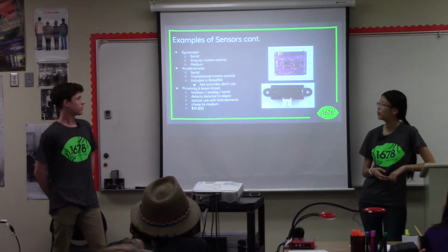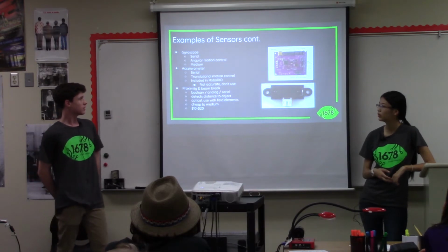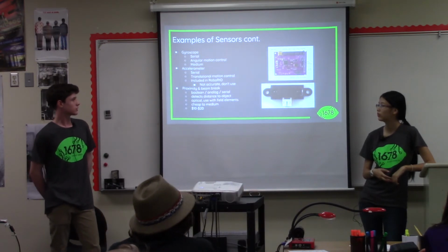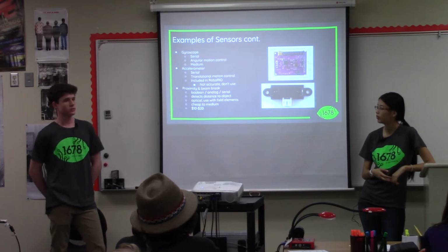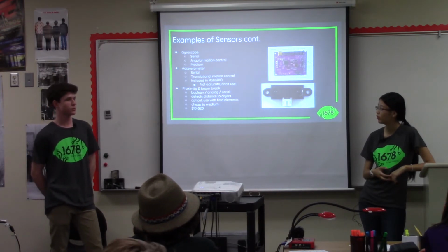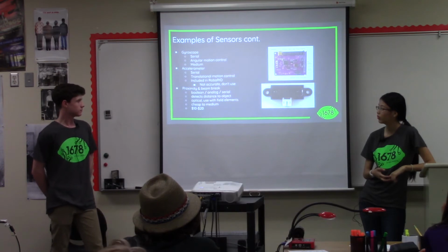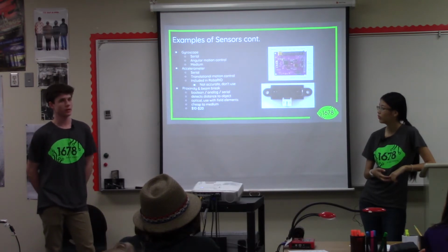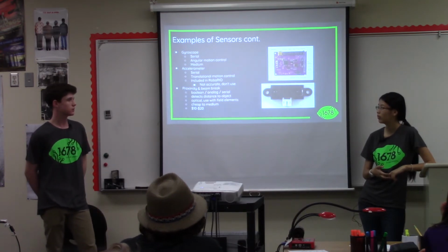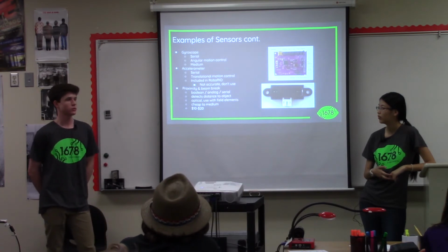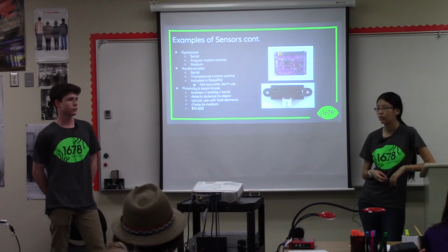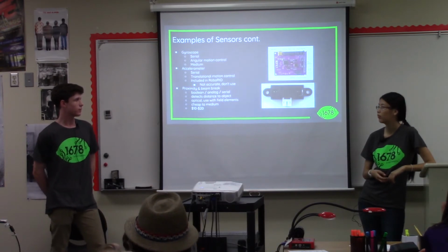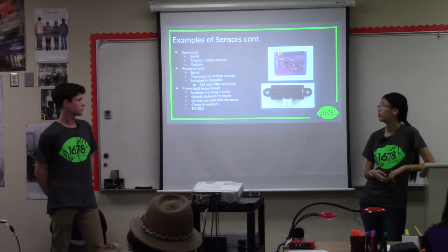And there's also proximity and beam break, which can give Boolean, analog, or serial output, and this would be used to detect distance to objects. It's run with light, and you have to consider what your light would be reflected against, because some materials reflect light differently and might affect the accuracy of the sensor.